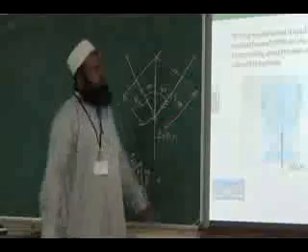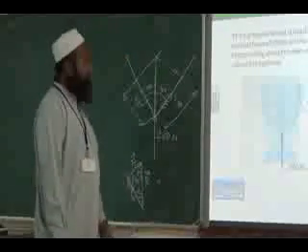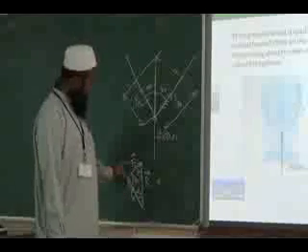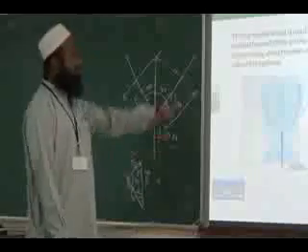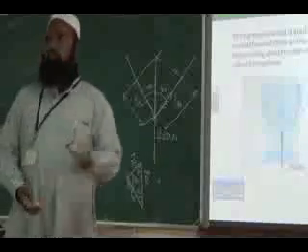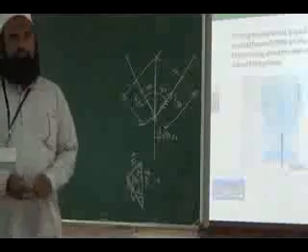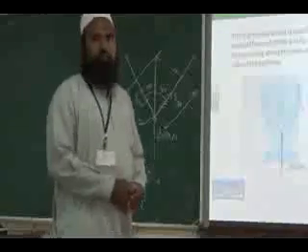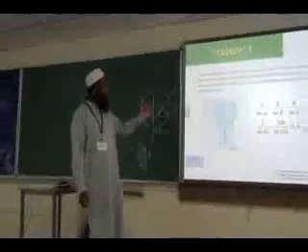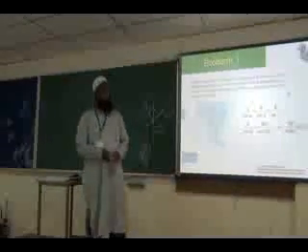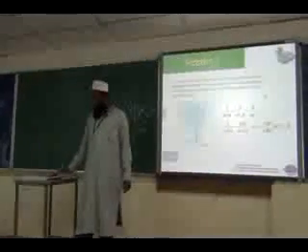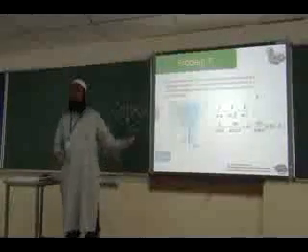So consider the sine rule. A by sine 30 will be equal to the resultant by sine 120. You can find out A as well as B, the same value. Resolution of forces can be obtained by considering either the graphical approach or by using the sine law and cosine law. Any doubt in this problem?